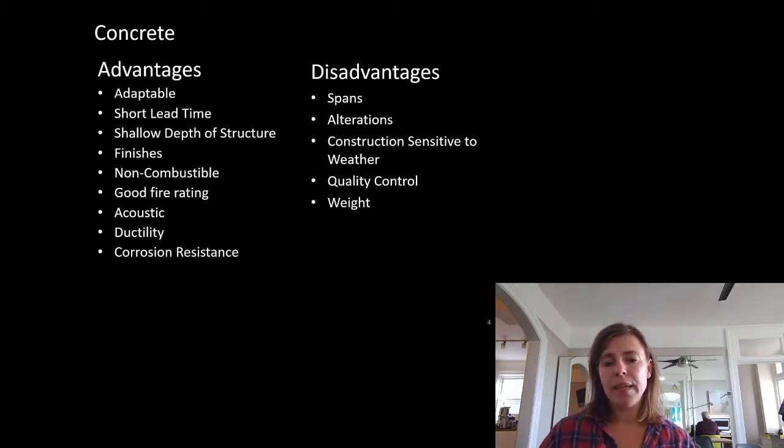Concrete is, as much as our steel is made in an industrial plant, where there are chemists on site testing it, a really scientific, thoughtful process. With concrete, we say this is how strong we want it to be, and a bunch of people throw a bunch of stuff in a truck, it gets mixed up on its way to site, and they pour it out. We literally do not know if it's strong enough until after it's been cast, because they take little samples of it and test it at 7 days and 28 days to prove that it is in fact strong enough.